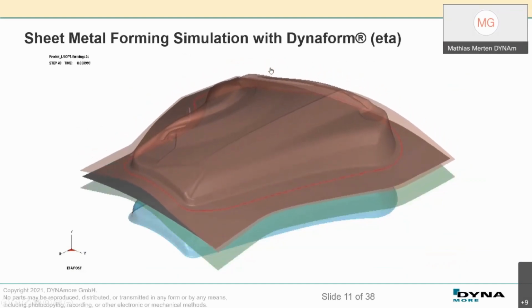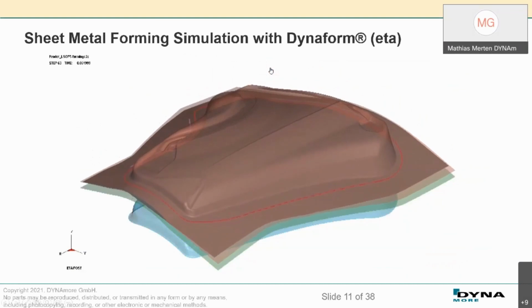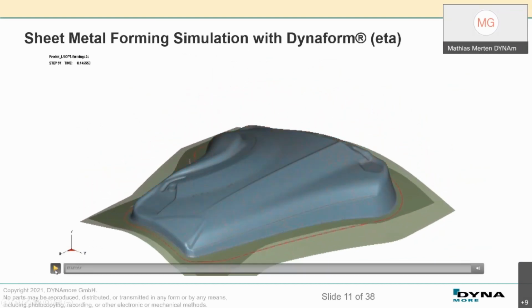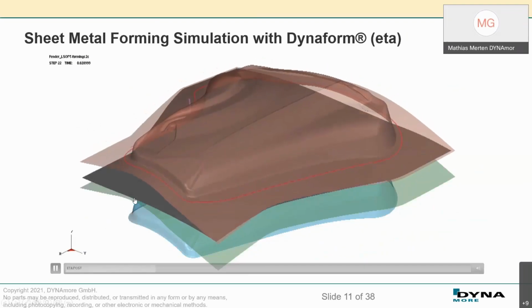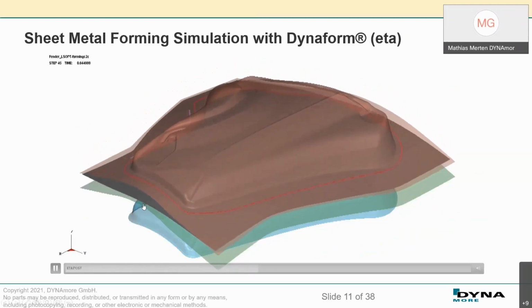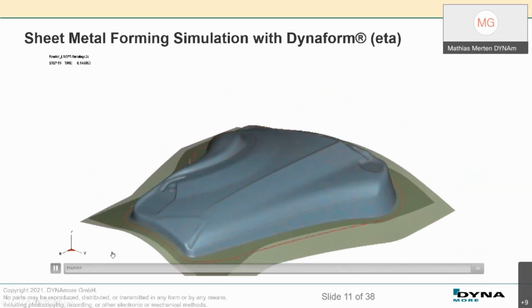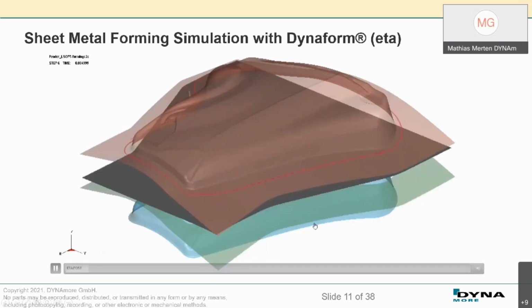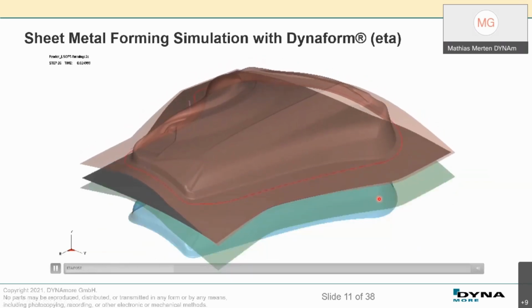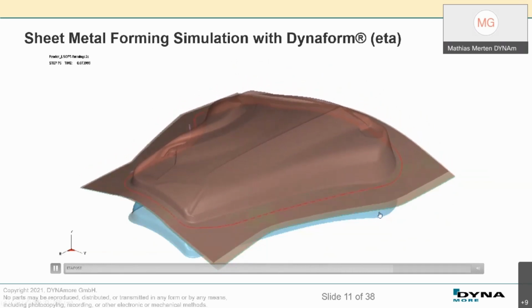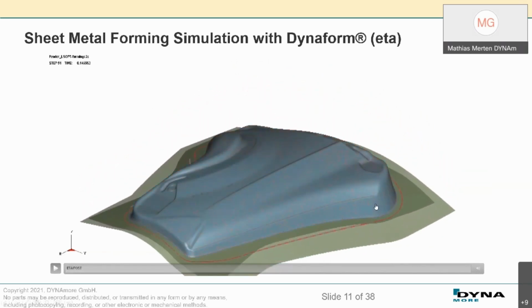For this video, I have chosen more D3plots, and this is the result animation, which you can see quite well that we have these dynamic effects inside the blank due to the explicit time integration and the time scaling. So you see these oscillations everywhere. And additionally, what can be seen for the process, for example, here we have some wrinkles which are flattened out when the die reaches the bottom dead center. So that is also well known.